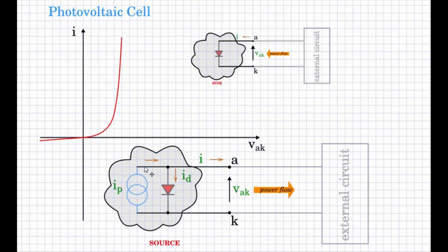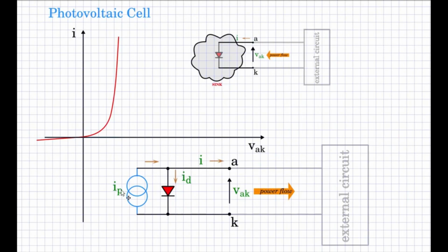Let us study it just a little bit further before we develop the equations for this. IP is the photocurrent, which is directly proportional to the solar intensity, the solar power that is incident on the surface of the panel. If IP is 0, that is under dark condition, the characteristic is like this, with the bias at the x-axis line.